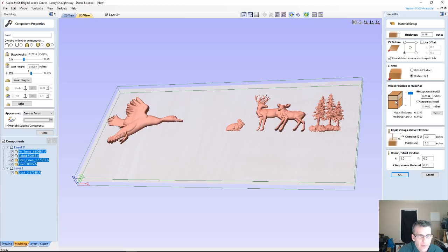So from 0 to the bottom of that model, the total depth is 0.4462. And since I'm carving from the top down, not the bottom up, in order for me to get to that 0.4462, I have to subtract that number from 3/4, which is the top of my board, and that gives me the depth of cut that I need to get to that depth from 0. Does anybody understand that? Or did I just confuse the whole situation? Tell me if you're confused.